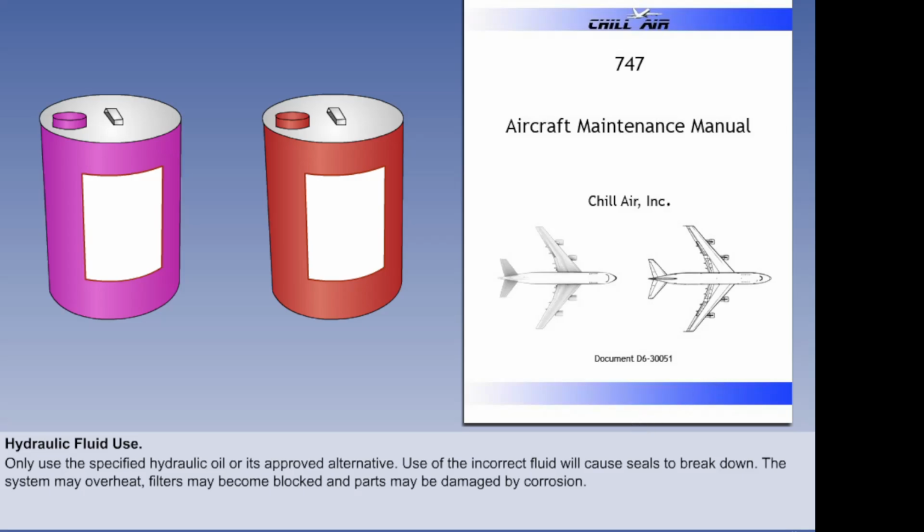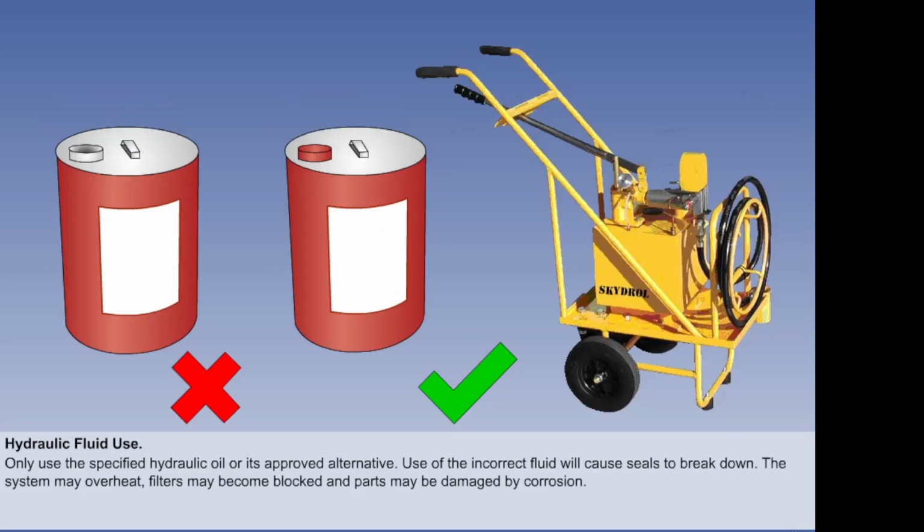The colouring of the fluid assists in its identification, and also assists in finding hydraulic leaks. However, it must never be used in isolation to identify a type of fluid. The fluid may not retain its original colour when it has been in use for some time. The specification can only be confirmed by consulting the aircraft manual and by only using fluid from sealed containers or the appropriate replenishment rig.